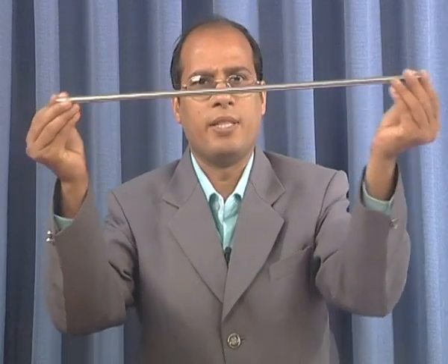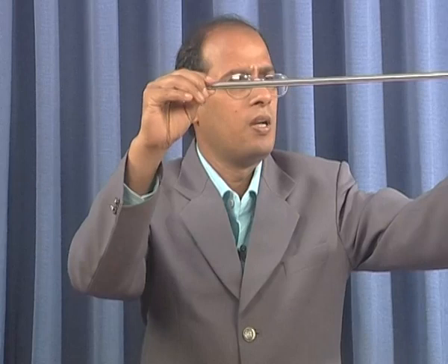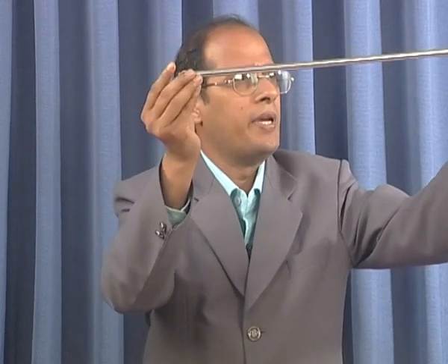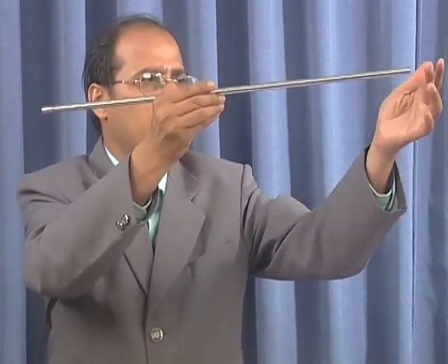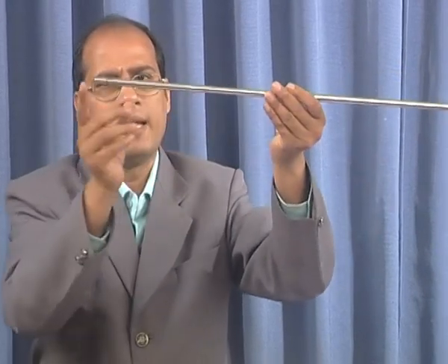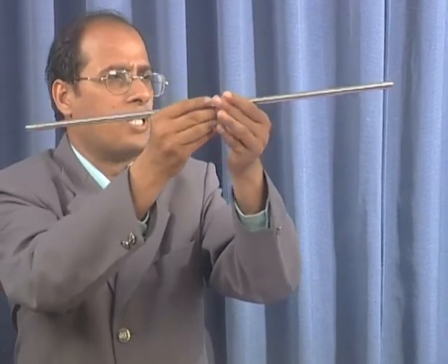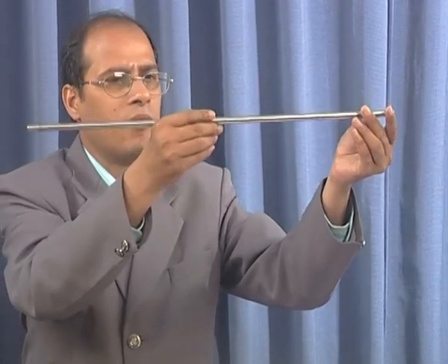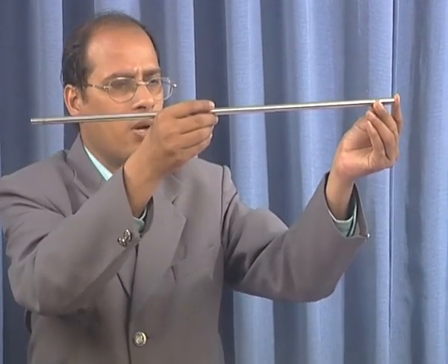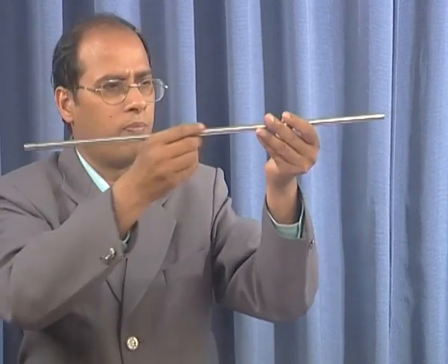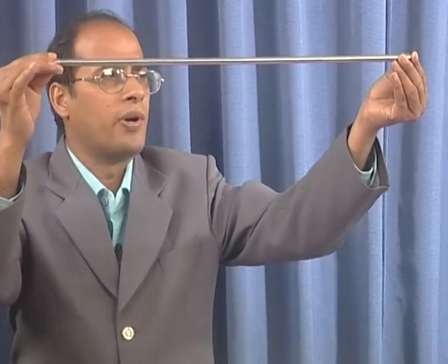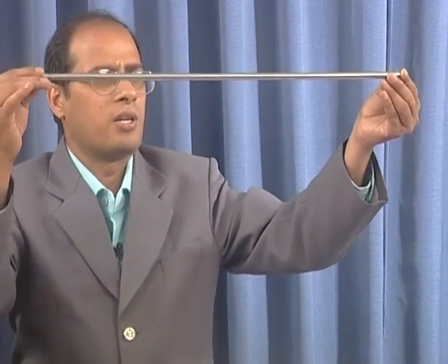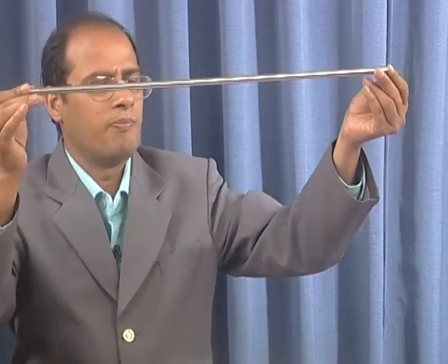in this rod you are fixing both ends, and when both ends are fixed, there is no vibration at these ends. So you have taken theta 0 equal to 0 and theta L equal to 0, so the mode shape phi 0 equal to 0 and phi L equal to 0. When you are taking b equal to 0, the total expression phi x will be equal to 0, and that will lead to the trivial solution. That means there will be no vibration of this rod, or the rod will not rotate, but as we are considering the rotation of this rod, we have to take b not equal to 0.